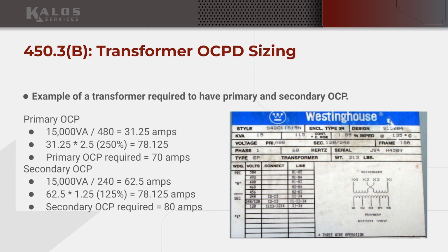And normally we'll see a larger gap between these, where the primary and the secondary aren't so close together. It's just this example that I picked, being a 240 volt secondary versus like a 208 or something. It's just the way this math worked out. It put it pretty close. I think typically we might see something like 45 amps on the primary and then a higher overcurrent protection on the secondary. And there may be other reasons for that. Maybe the job was engineered just differently.